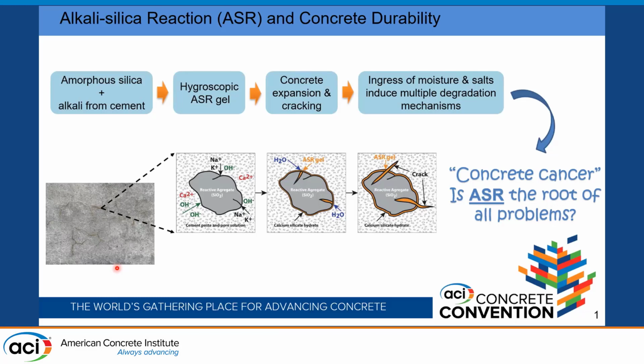In the presence of cracks, external moisture and aggressive sources can ingress into the concrete, which can result in multiple degradation mechanisms. This is why the ASR is also called concrete cancer. And when we consider the entire chemical reaction and deterioration process caused by ASR, we found that the ASR gel is the most critical part.